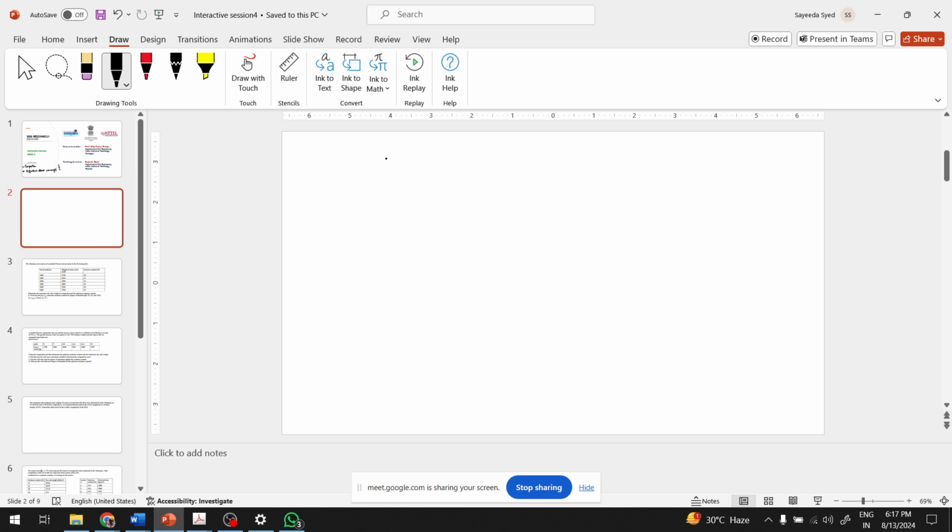All you need to know is that when you have some loose soil in the field and you want to build a building over it, this loose soil will settle down as you put load on it, because it is not in its optimal configuration. So what we try to do in compaction is put load on it by means of rollers.